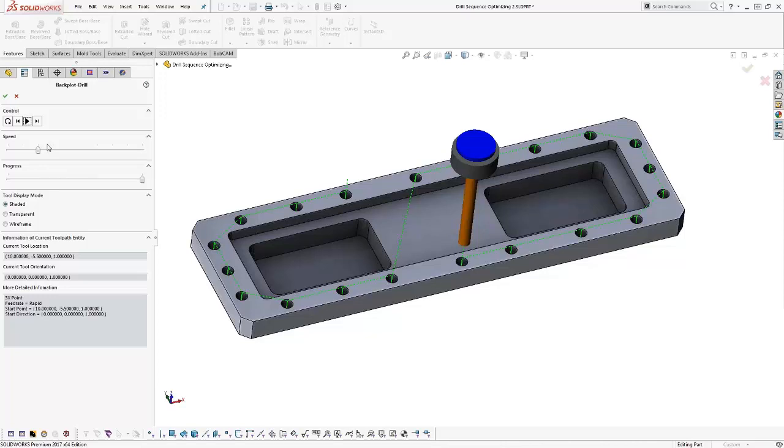So closest a lot of times is a great optimizing tool to quickly get through the holes, but when you start adding safety in there, sometimes that pick order really helps to control where it's going to cut in. I mean, yeah, sure, you can raise your retracts, and you could also use different groups to change where your retracts are. So you do have different options for that, but this is a really nice one here, okay?